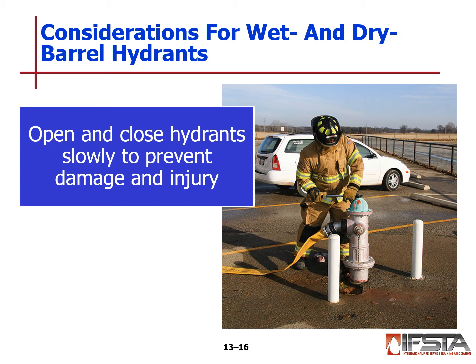It can possibly do physical damage to the inside working gears and impellers of your pump. So we open slow, we close down slow. The same thing if we slam our valve underground shut really hard, we're hammering water back. We could hammer water back into residents and do damage to toilets and plumbing fixtures and things like that.